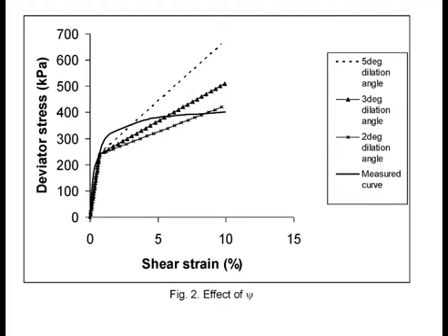But I would say that it doesn't mean that if you exceed it, you will definitely collapse, because most of the time the triaxial test stress strain curve is conservative, because most of the test specimens are disturbed in some way. As a result, the measured stress strain curve is probably well below the actual stress strain curve. So there is some margin, but you don't know how much the factor of safety is. That's the danger, sort of like going towards a waterfall, but you don't know how far you are from it.